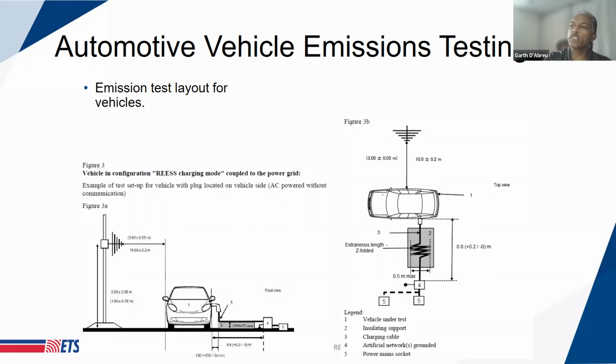And it allows for flexibility in the connection points of the charging harness. It gives guidance on the layout of the charging cable, positioning relative to the vehicle and the ground plane, just so that you have a good chance of repeatability of results. If you are in a position where there's not good control of setup functions within the test, then it means that repeatability is going to be very, very difficult. So all of this is really aimed at providing a standardized method of performing the measurements so that you have a good chance of getting repeatable results.